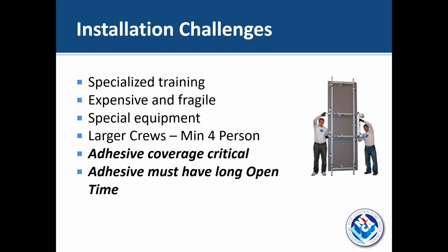Panels in thickness are usually 3 millimeters, 5 millimeters, and up, maybe 6.5. So very thin material. And because of that, in terms of an adhesive, the coverage is absolutely critical. If you think especially on a floor with a tile so thin, you really want as close to 100% coverage as you can get. If you have any voids underneath that tile, it can easily lead to cracking or even punctures.